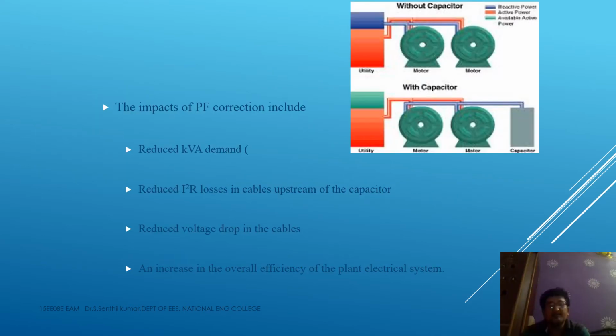Some of the impacts of power factor correction include that it may reduce the kVA demand, reduce the I square R losses, and reduce the voltage drop. Care should be taken in the sizing of the capacitors. In the figure we have shown the motor with and without capacitors.